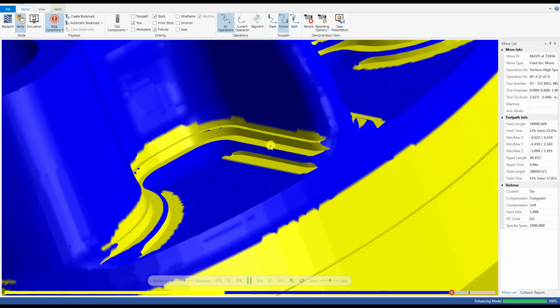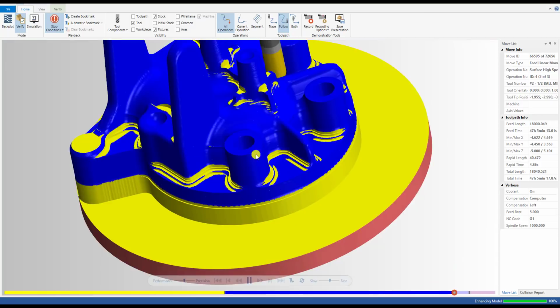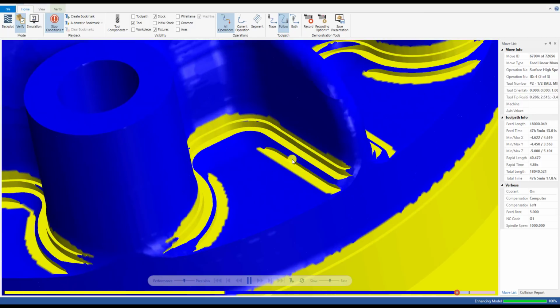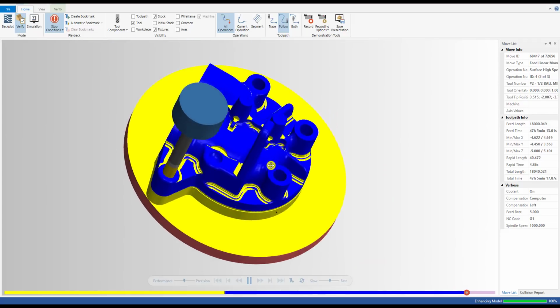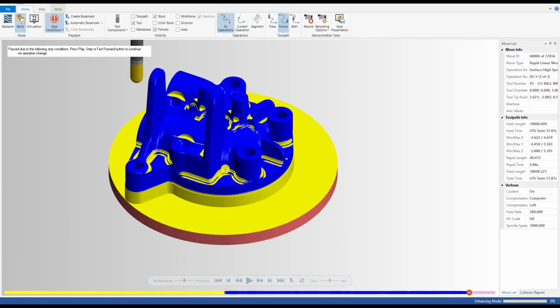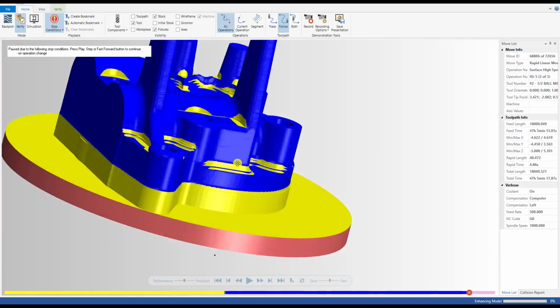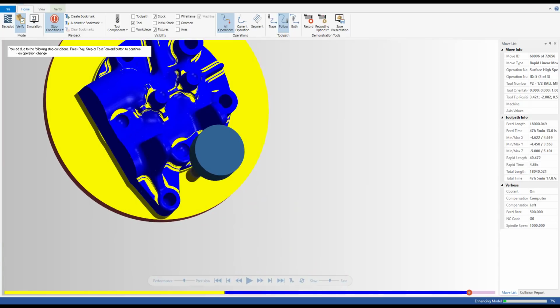The corner here still has the mark of the roughing tool, and the big finish tool cannot clean this corner. Yeah, this is a nightmare. You don't want it. You can see we have a lot of marks from the roughing tool here, here, and here.